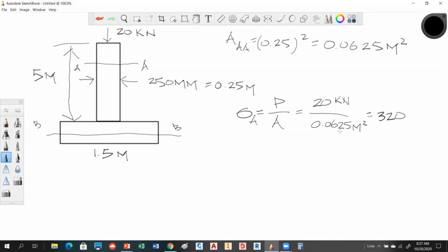So the unit of this would be kilonewtons per meter squared. Another way of referencing a kilonewton per meter squared or a newton per meter squared is what's called a Pascal. So you could also call this a kilopascal. So these are exactly the same. So you got to watch that when you get into metric, okay? Metric is a little trickier because it's a real big unit game, okay?